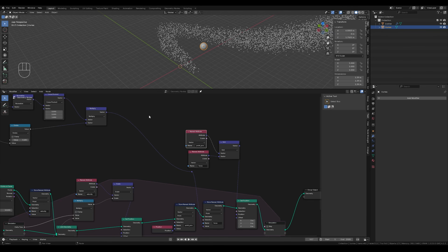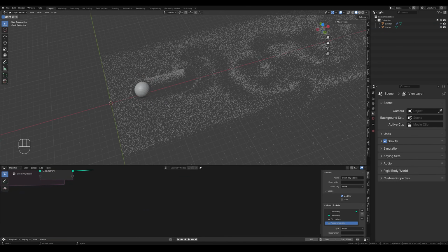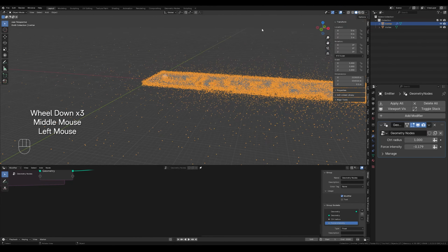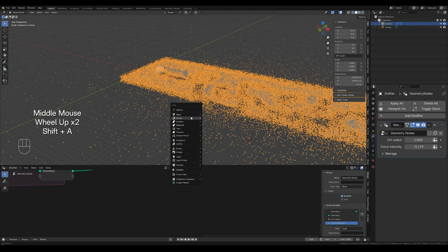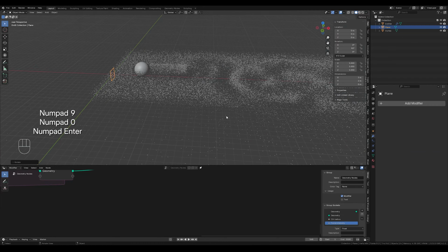This blend file will get slowed down or crash from continuous spawned points. So we can set a point deletion system similar to bounding box beyond which points will get deleted or destroyed. I will use a plane for this. So let's add a plane and resize it.